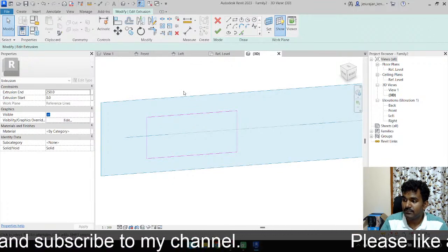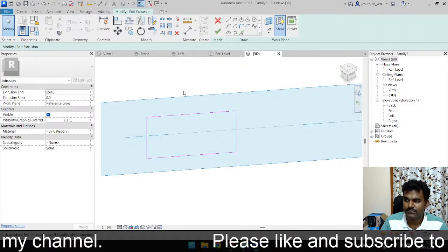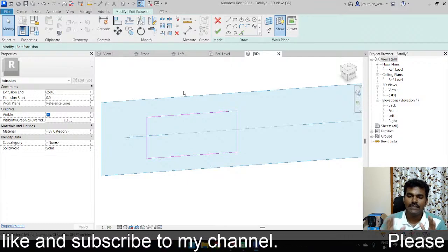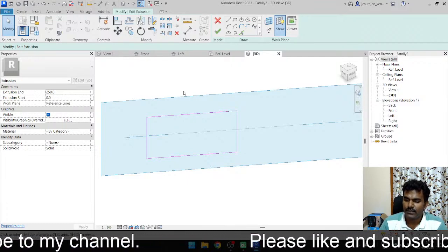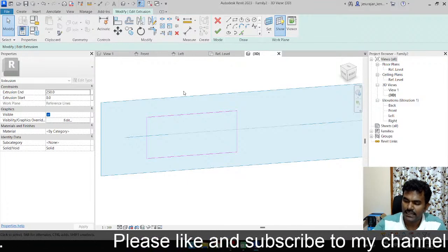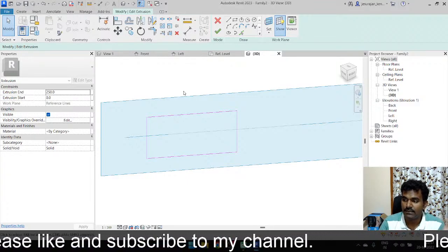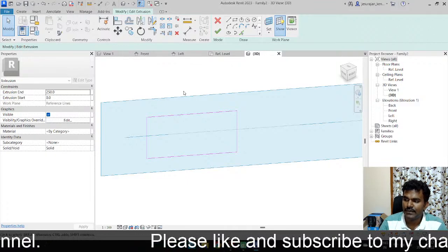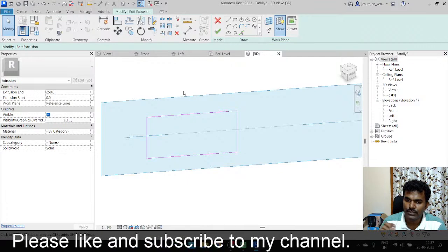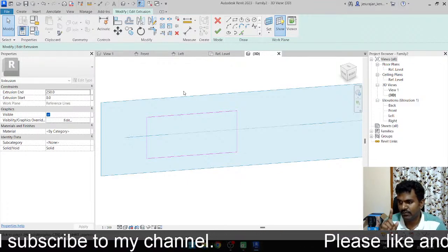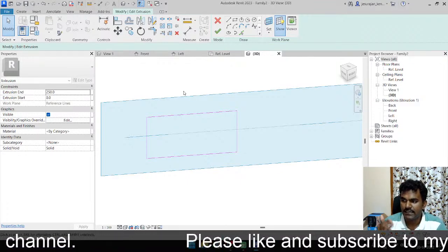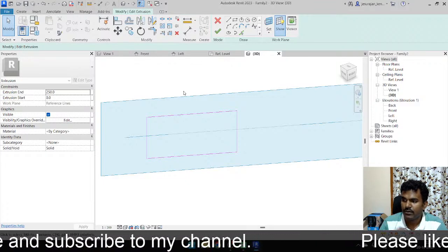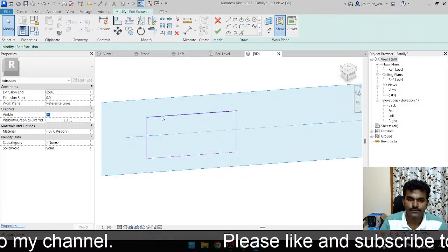Audio is okay now. What's the difference between type and instance? If a parameter is available when you select the element and check the properties, that means it is an instance parameter. If you select an element, go to edit type, and you can find that parameter inside the edit type properties, that means it is a type property. I hope now you will understand.